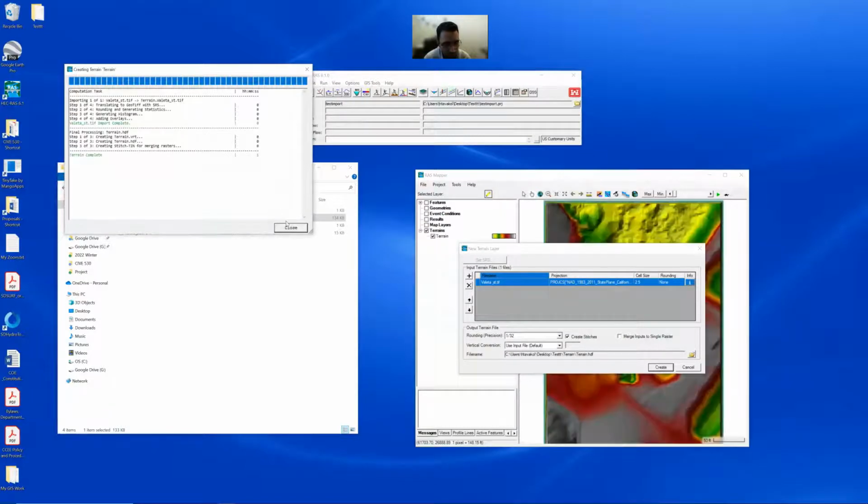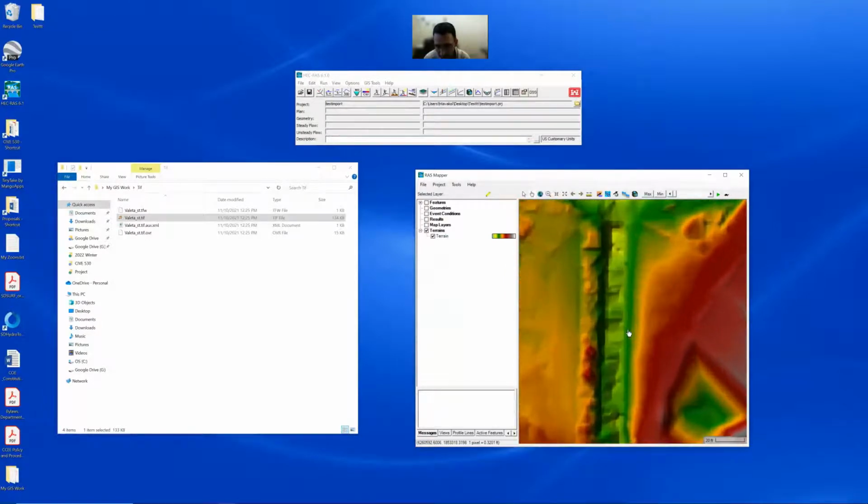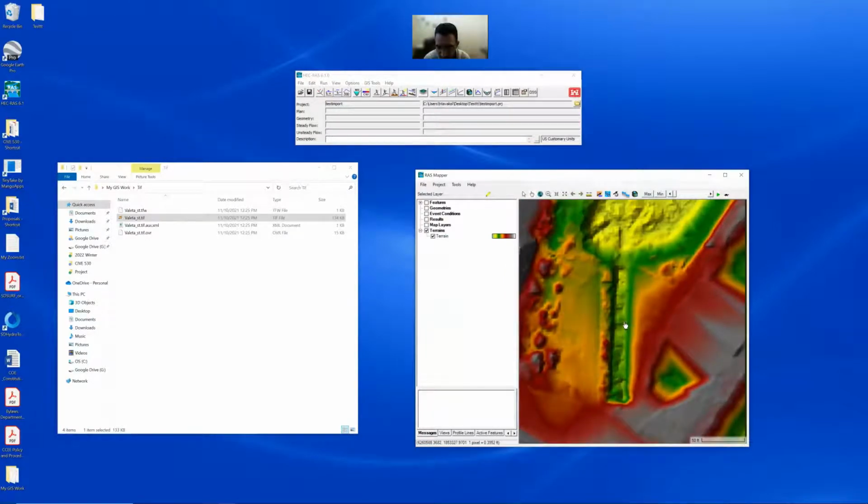So do some processing, boom, you now have it. So it's showing up in your HEC-RAS, your channel. So that's basically a major milestone. After that, you're basically setting up things which are gonna be much quicker than doing it manually by hand for station elevation and stuff. So now that you have this, you of course want to save and also save your main window. Then start drawing things.